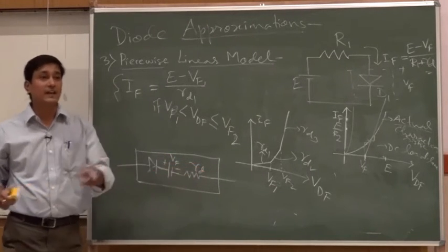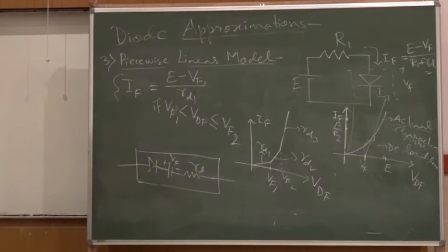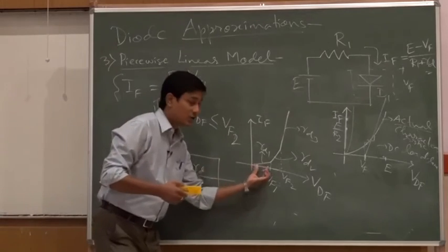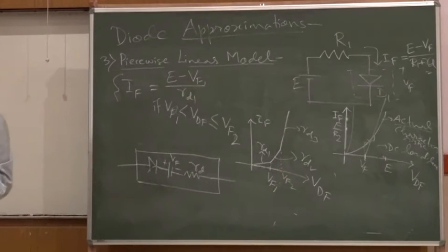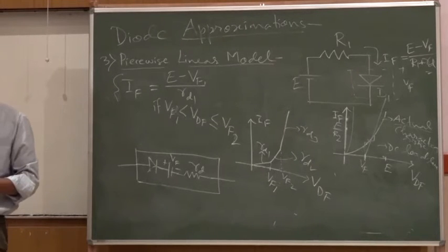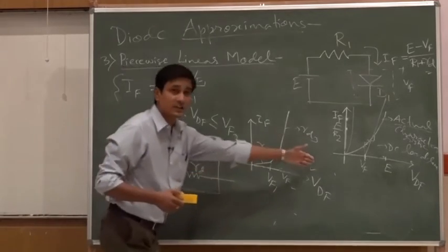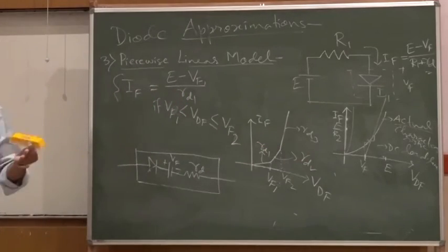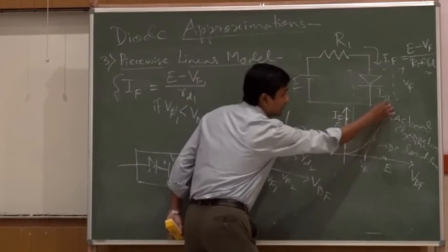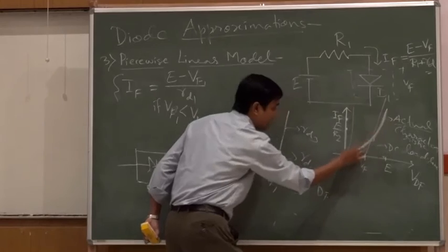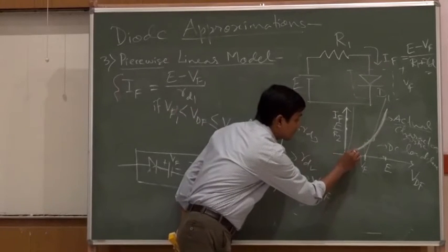Okay. But for that I have to track what voltage is coming across the diode. Is it within this range, or this range, or this range? That means complexity in your system analysis is becoming more, which is quite obvious because you want to get a more accurate value. So how many RD can you consider? I think multiple, n numbers, as many as you can afford in your circuit analysis. Now if I make this piecewise linear approximation of the actual curvature which we considered at the very beginning, now you consider a small section of it.